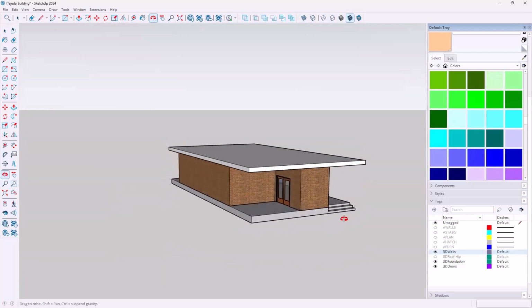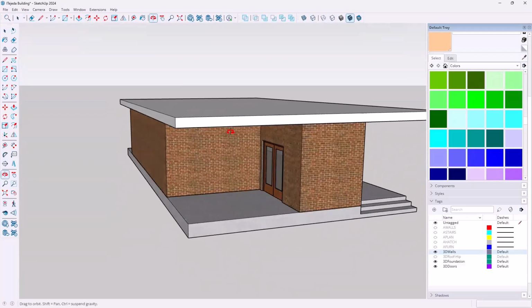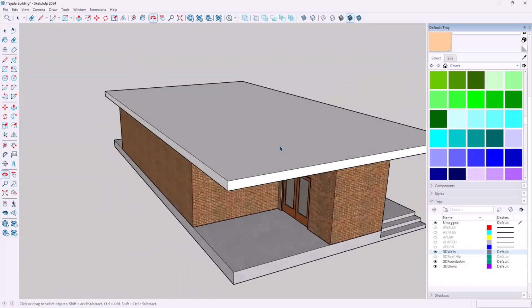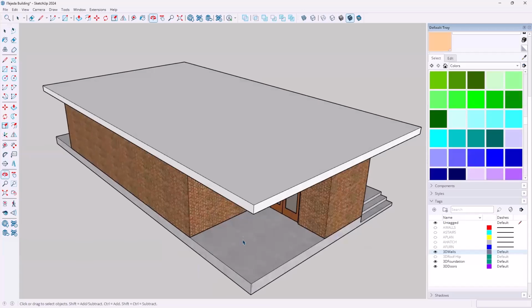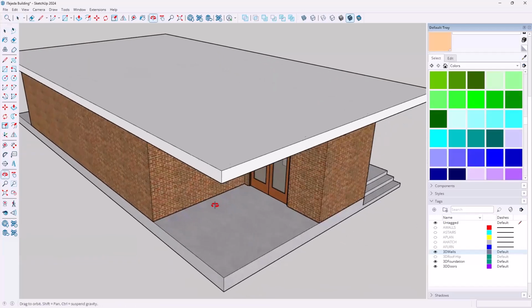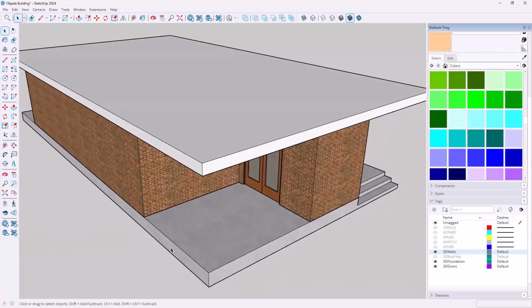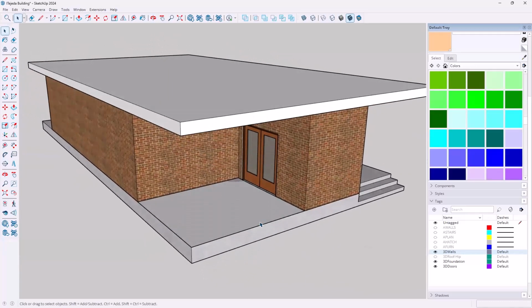And then if you wanted to, let's say that I wanted to maybe have an opening right here, just because I want to show this to you. Here's what I would do. Let's say I know that I wanted to somehow be centered in this space. So I'll do this. I'll draw a rectangle right here. I'll take it across. And notice how they're coplanar, those spaces. By the way, I tapped the space bar. This is coplanar, and it could be a little confusing. So I'm going to turn off my 3D foundation.